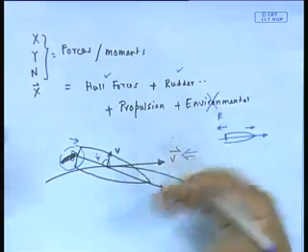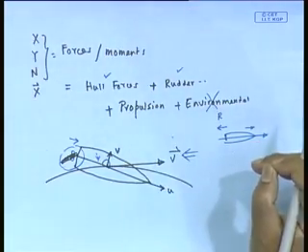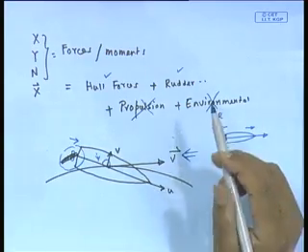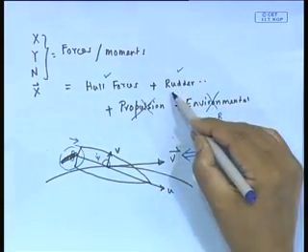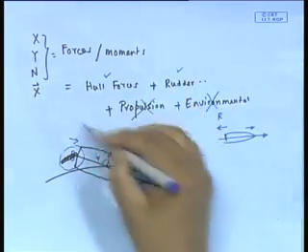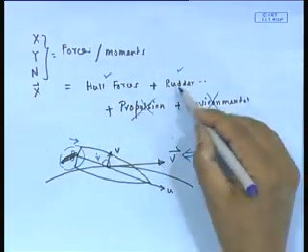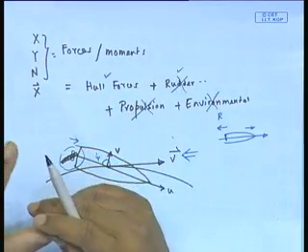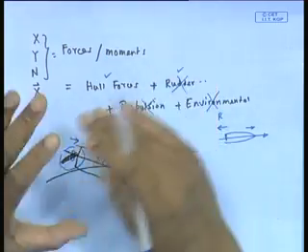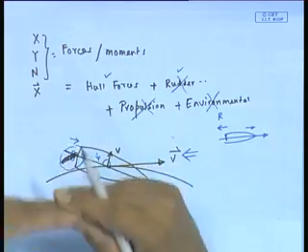Propulsion and resistance cancel out, because when it goes at steady state at a given speed, propulsion minus resistance becomes 0. That is why it is going at a forward speed. So, I will not have any propulsion force here for this consideration. I only want to know this side. Rudder I do not have because I am not applying rudder. Actually, we are trying to find out firstly the hull forces, we will model them eventually. When I want to study just a bare hull with rudder fixed, not applied, the rudder is kept fixed, it becomes a part of the hull, I do not operate it.